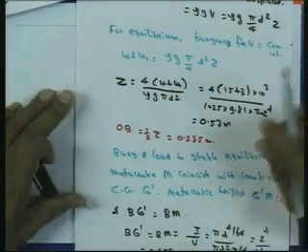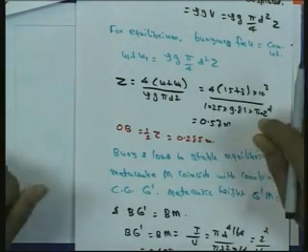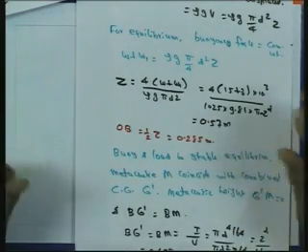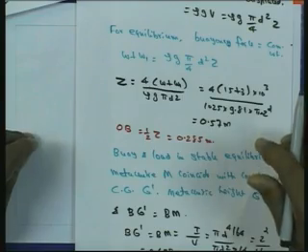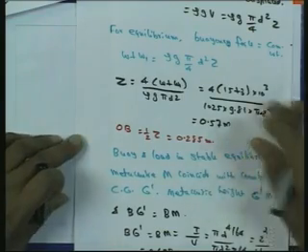Now the buoy and load is in stable equilibrium. As per the problem statement, the buoy and load is in stable equilibrium, and the metacenter M coincides with the combined center of gravity G dash. So the metacentric height in this case, G dash M, is equal to 0.